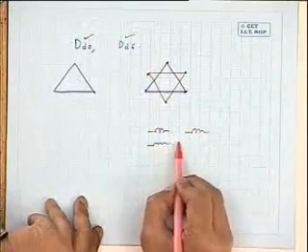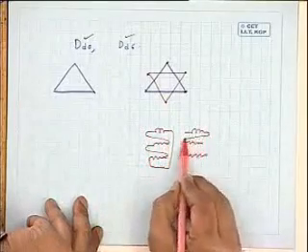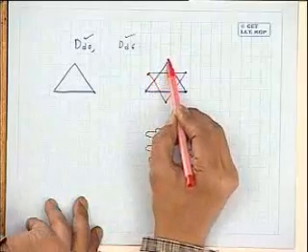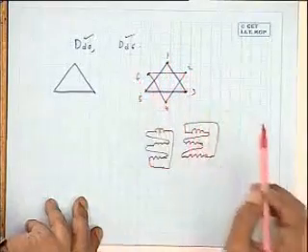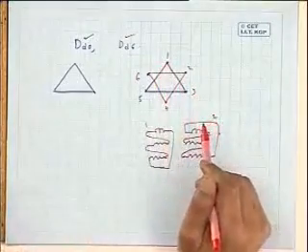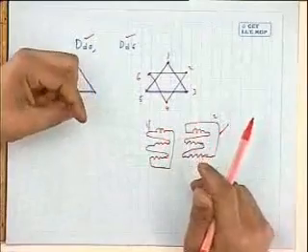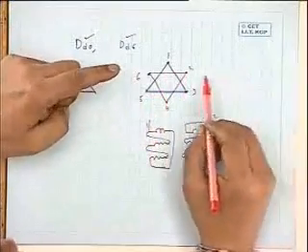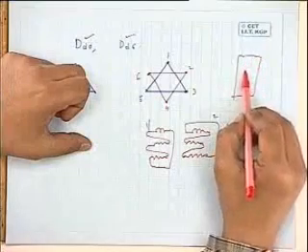However, see, there is no interconnection. You remember, these two sets of secondaries, if you look at them, I will not draw with terminals. One will be connected like this, another will be connected with proper terminal markings, this way. Now, these points I make some marking, say 1, 2, 3, 4, 5, 6. Suppose this is 1 here. Some 2 will come from this side. If I connect a voltmeter between 1 and 2, will it read? These are isolated. Balanced six-phase voltages will be there, provided you connect a balanced six-phase load. Then that return path will be available.